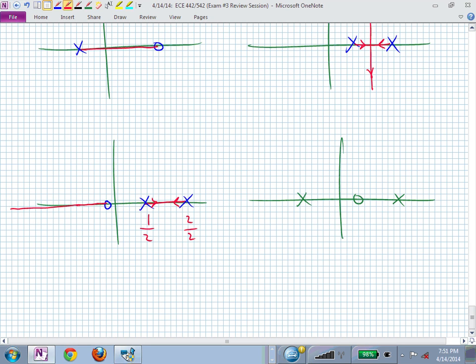What's the pole zero excess? 1. Where's my asymptote? 180 divided by pole zero excess. Where's my asymptote? 180. It's that sort of easy or trivial one. Hopefully that leftmost pole is inside the unit circle if you're trying to stabilize this with a constant gain controller.